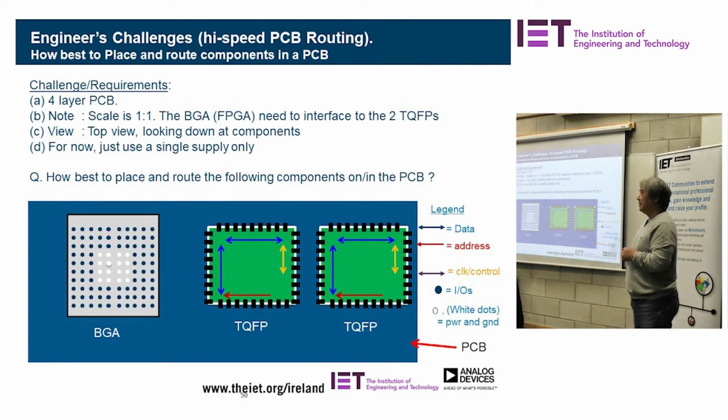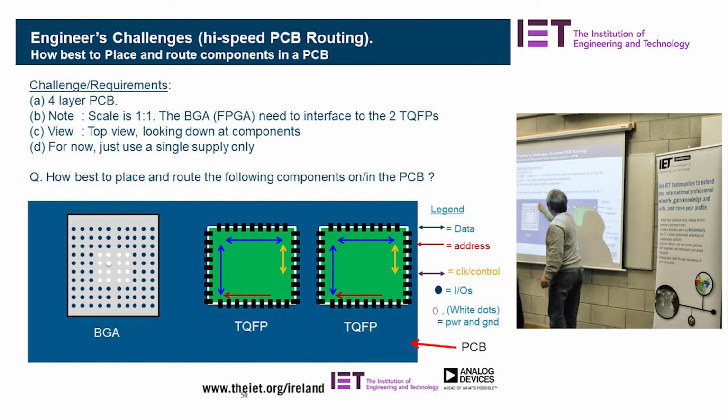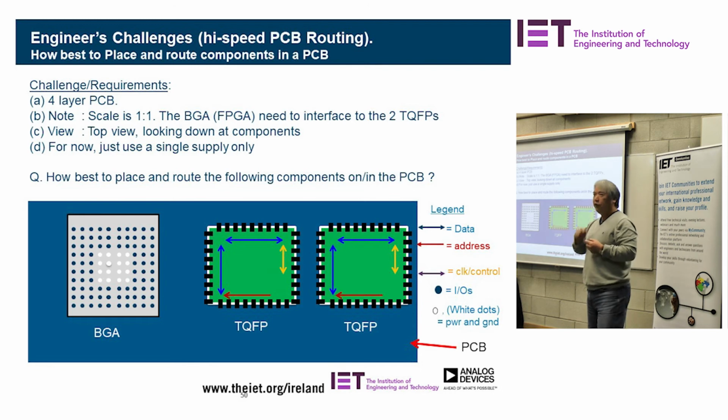So you could place them top and bottom, but then you have a problem because with this FPGA, when you place top and bottom, the wires still need to cross over back and forth. If you put it on the other side, so that's in the middle, you cannot put anything below because those pins propagate right through it. So nothing can go in the middle. I need to go across it. If you go across, depending on which way it is, you might have crossing wires. That could work, but it's not efficient enough.